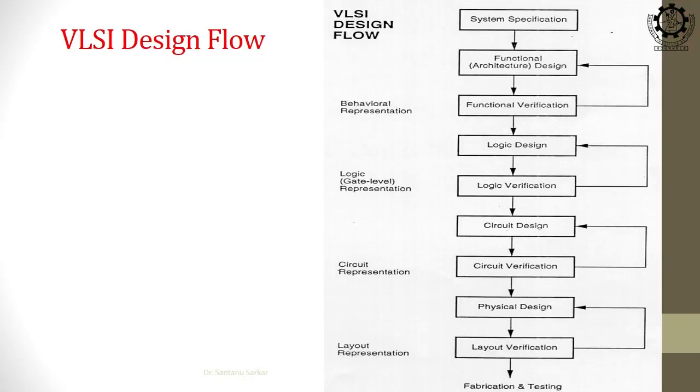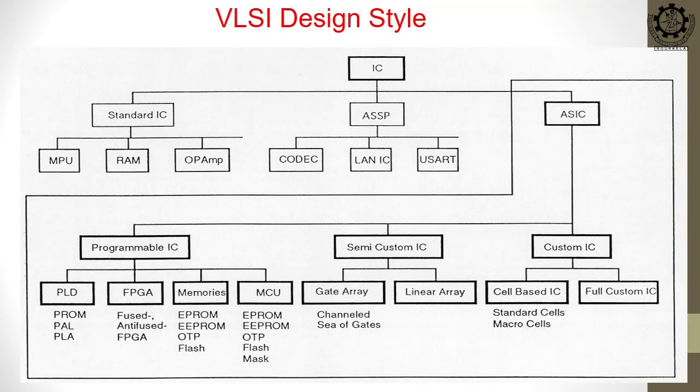So, that we have discussed several times, and we have functional verification at each step, that also we discussed. So, we will be having functional verification, logic verification, circuit verification and physical design verification, and as we know, at each level we should do a check on whether it is satisfying our target specification. Otherwise, what will happen, if you think that at the end you will do the final checking, at that time much time can be wasted. So, at each step you should have a verification, and if it is working then you only go to the next level.